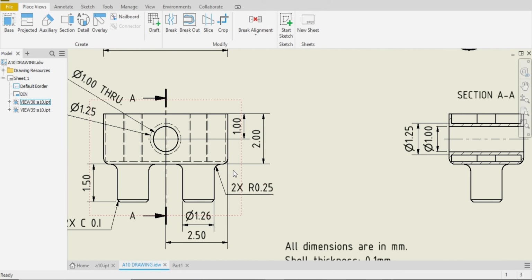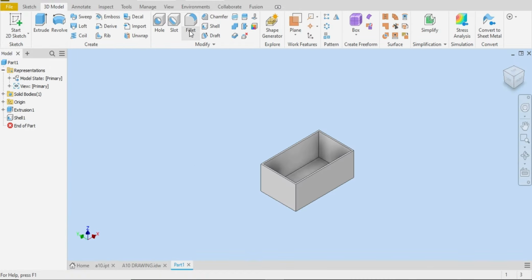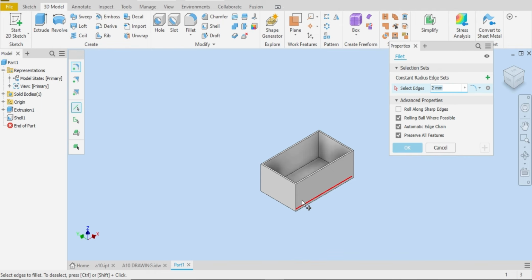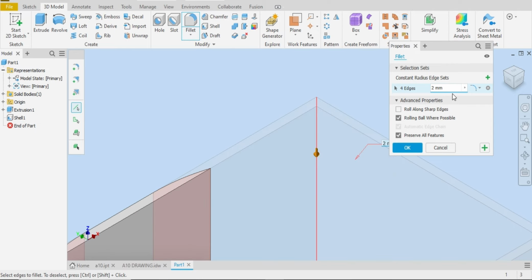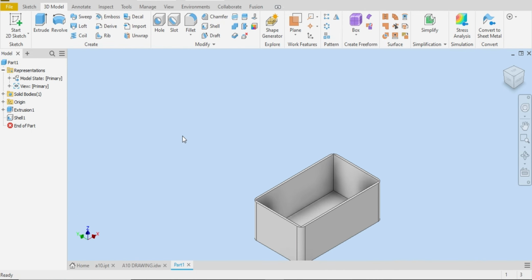There are fillets, 4 fillets at the edge and also inside. Look, 4 with radius 0.25 inside, and also outside, meaning 8 fillets. So let me choose all the edges, the outer ones first, and now type 0.25. Let me select OK for this.